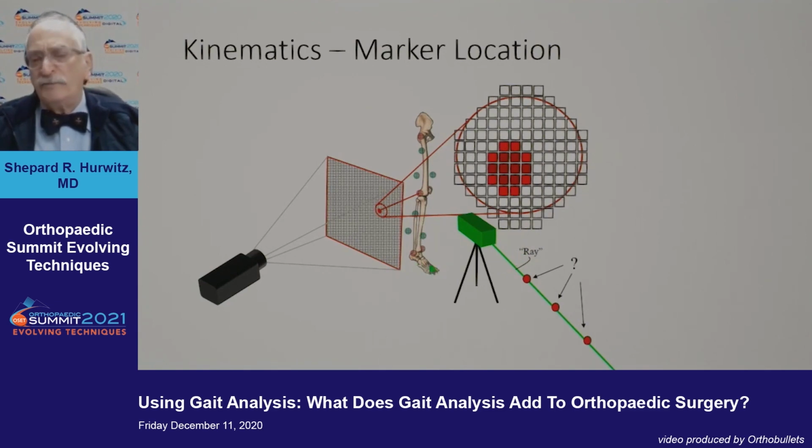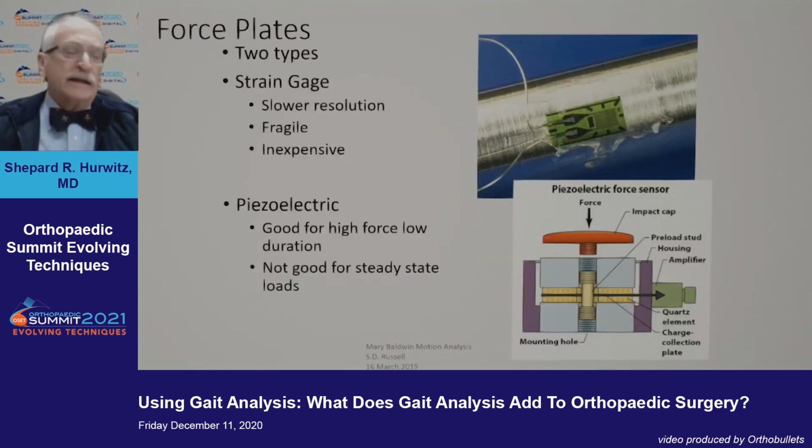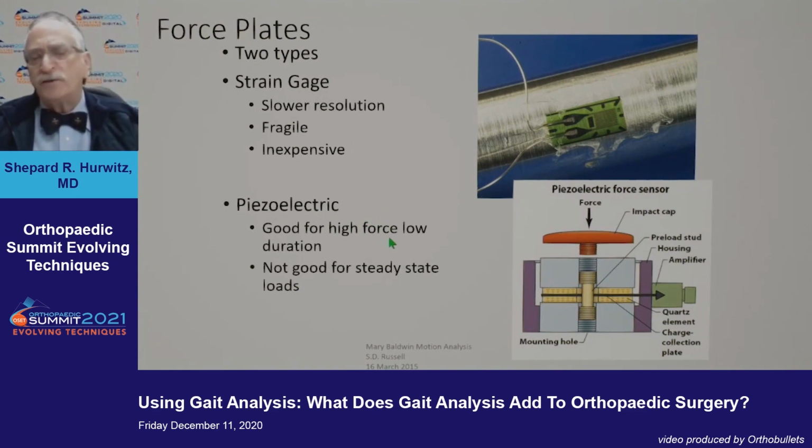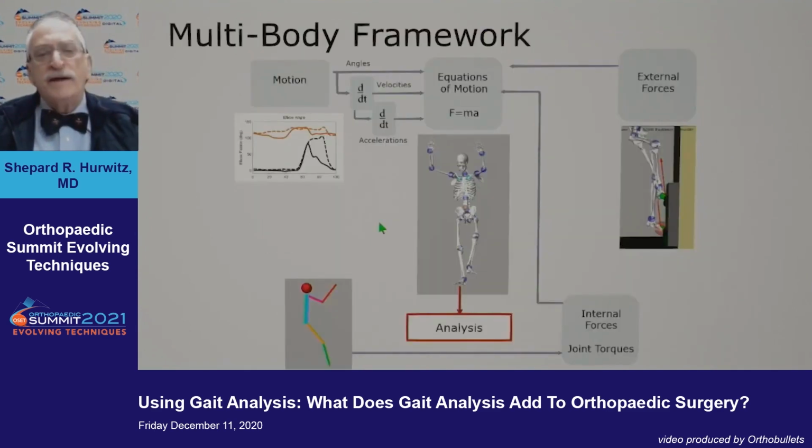And you add to that, when the foot contacts the force plate, you can determine shear, you can determine axial load, you can even determine whether there's axial rotation going on at that instant when the foot meets the force plate. The force plates that are most commonly used are a strain gauge variety, the piezoelectric, much more expensive, much more finicky, but they can give you better measurements, more accurate measurements for high force. That is, you're having someone jump and see how they take off and land rather than casual walking. So once again, the science and the engineering move on.